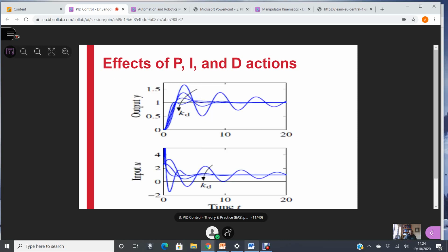Now, what you'll see here is no integral action, just proportional derivative, then, no, I see. Okay, actually that's not correct. The integral action is there, because you can see steady state error is 0. So I roll that back. I thought it would be easier to show derivative action without including the integral. But you can still see the effect that as KD reduces, that's the direction you're going. So, in other words, if KD was to increase as well, you'll get more oscillations.